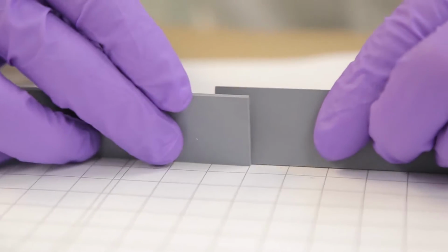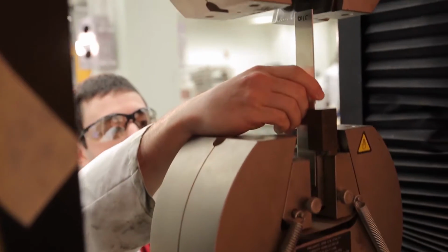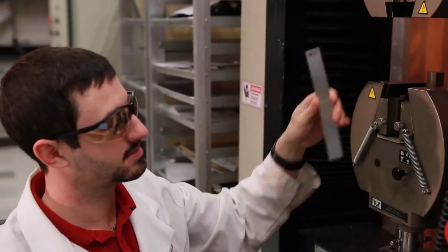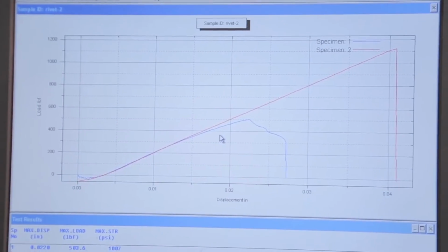One standard method for shear strength testing calls for the bonding of 2 test specimens overlapped by a specified area. The assembly is secured in a mechanical properties tester and is pulled in shear until failure. We record the load at breakpoint and calculate the corresponding shear stress. This is important because if a material fails at lower strengths, it may not be suitable for some applications.